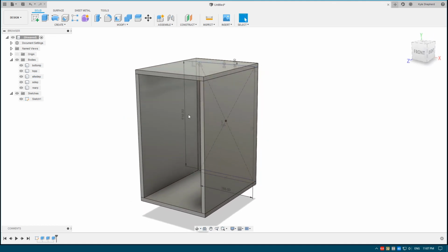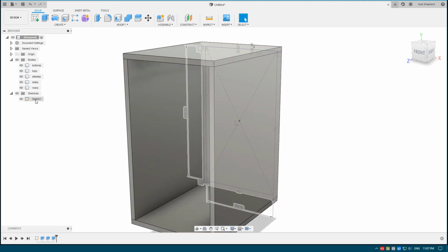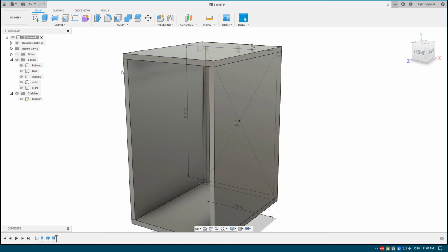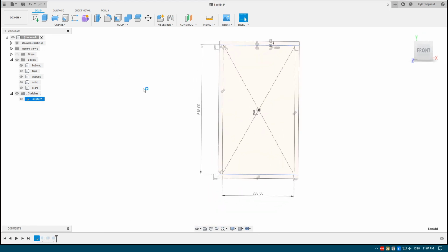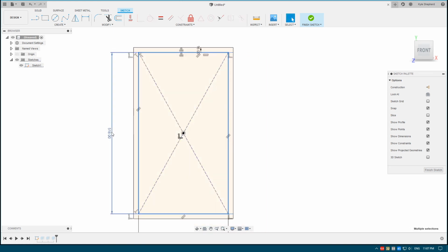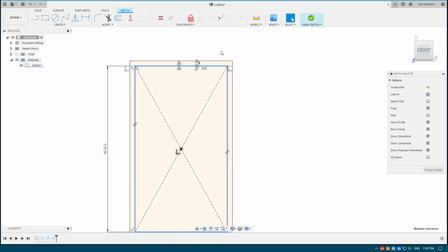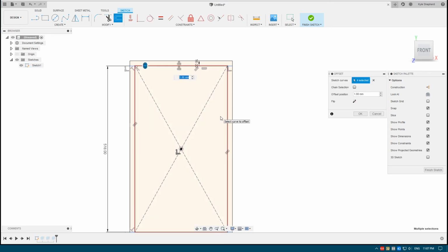Now we'll do the front facade. So I will do another sketch. I will edit on top of this sketch, because if you want to change these dimensions, you just stack it all up in this one sketch. So if you make one little change, the rest should cascade and properly apply to your model parametrically without stuffing up. So we're going to do another offset. So remember, we're working from our inner dimensions here. So we've got our 16.